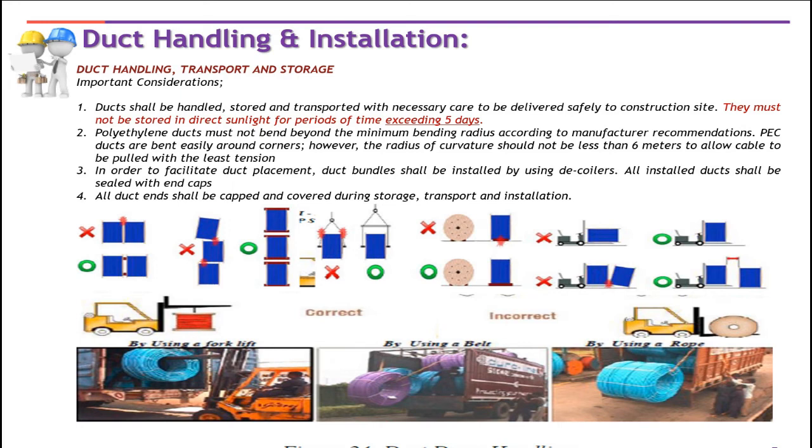Below are just some of the pictures which will guide you about the proper and improper way of storing the duct reels. Okay, first on the left, when storing duct reels, you shall make sure that reels have a separator so that they will not bump each other, causing them to be broken and later cause deformation to the ducts.